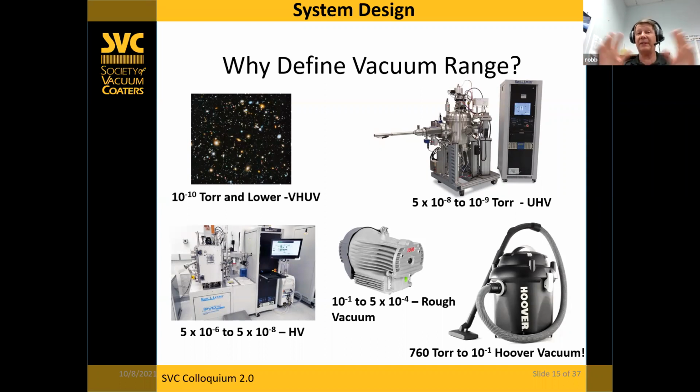And anything above 10 to the minus 1, we consider Hoover vacuum territory. So nothing is wrong with these ranges. You decide. Nobody's going to look at you if you say, hey, I need mine to operate at 5 times 10 to the minus 4, and we're going to try to talk you into 5 times 10 to the minus 8. That's not going to happen.